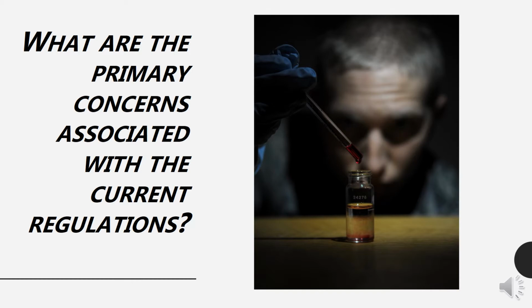There's much less data on disinfection byproduct formation and associated health risks of water consumption following treatment with alternative disinfectants. Recent work suggests that although alternative disinfectants may reduce the levels of regulated DBPs, these methods may promote the formation of unregulated byproducts that are potentially more problematic to human health. Increased formation of unregulated disinfection byproducts with alternative disinfectants is of particular concern if source waters contain elevated levels of bromide.